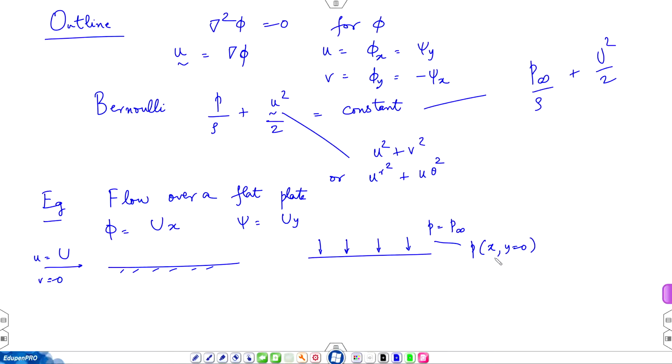Does it match experiments? Of course, you have to do experiments at the limit of high Reynolds numbers. So, these are typically wind tunnel experiments. Why wind tunnel? Because you can generate high velocities, you can place large objects in it, and viscosity of air is very small.